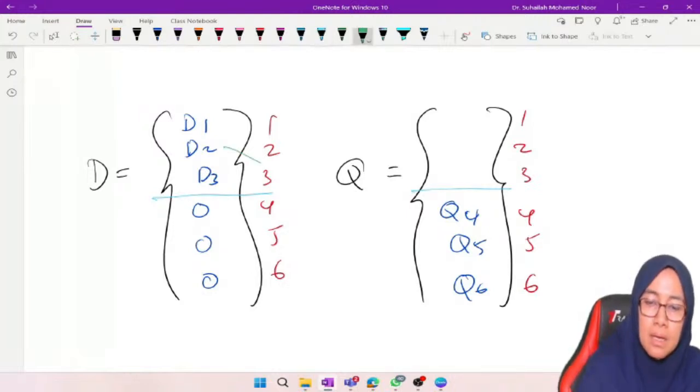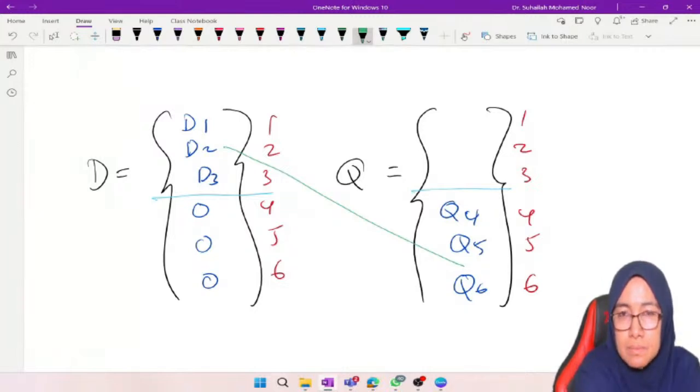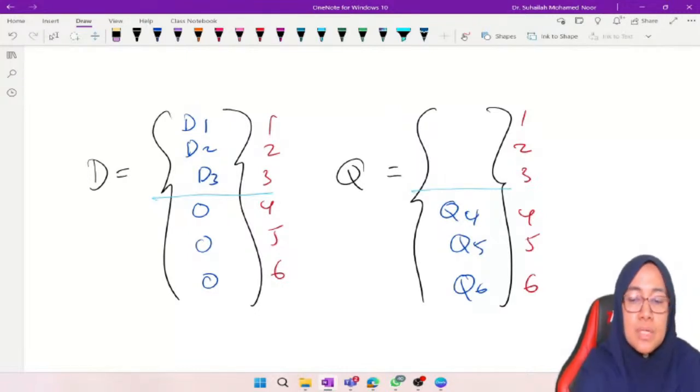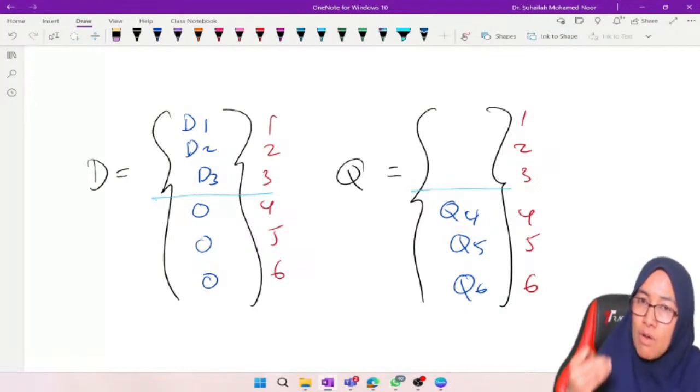This just refers to the opposite condition. So unknown displacement we determine in the unconstrained system. That's what I mean, by putting the green line. Unknown displacement is located in the unconstrained system, and unknown reaction is located in the constrained system. So it is always the opposite condition: unconstrained and constrained, known and unknown. So for Q1, Q2, and Q3, because it must be opposite with 4, 5, 6, because 4, 5, 6 is constrained, 1, 2, 3 is unconstrained, and the condition is always opposite.